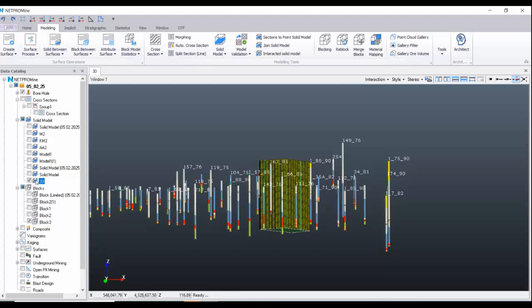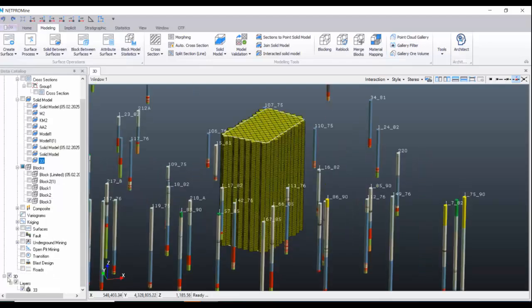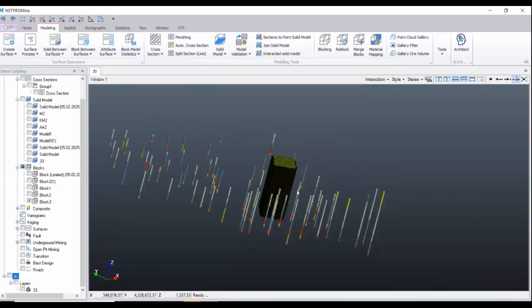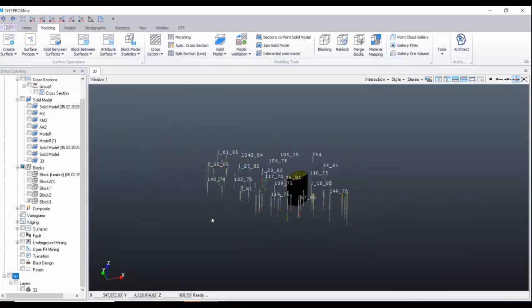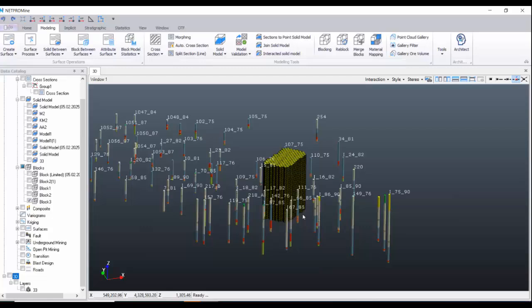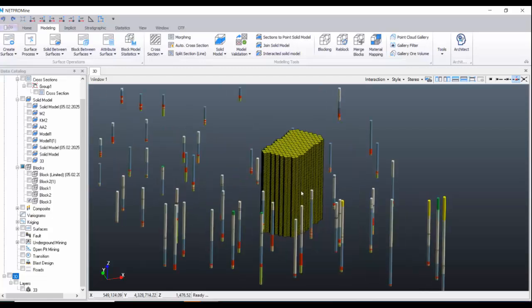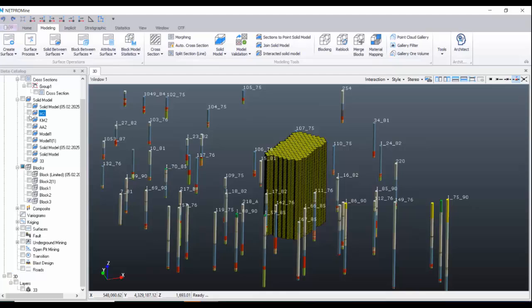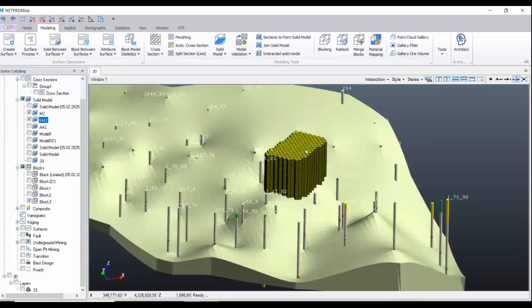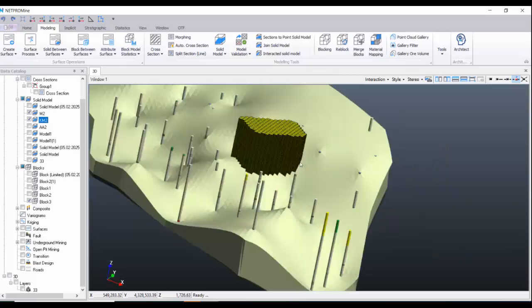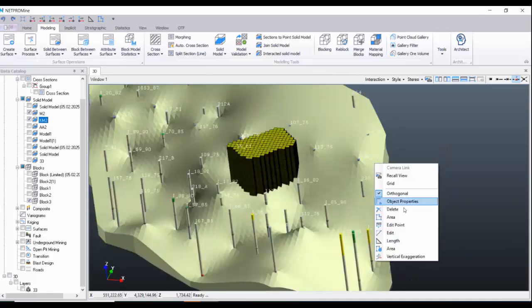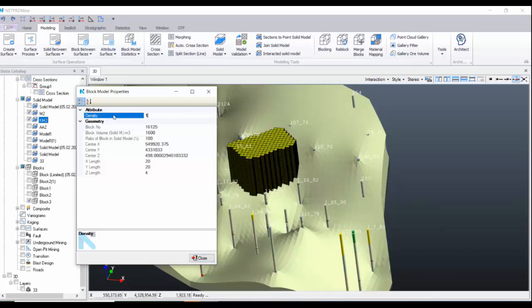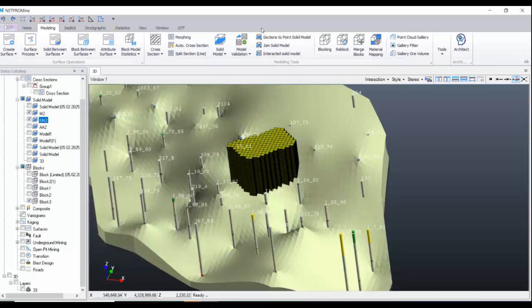All right. Now we created a block model by using that solid. But you can also create a whole huge block model as long as you assign the lithologies. It's going to be fine. Now we can move on to the material mapping. The block model that I just created doesn't have any attributes. So if we check on the blocks, it just has density information, which is a default. We are giving density 1 as a default. So now we can go to the material mapping.